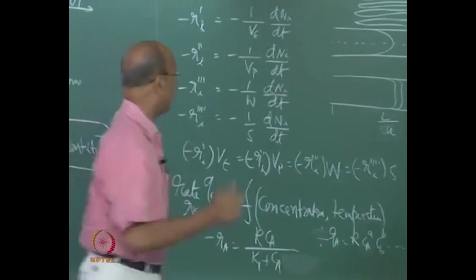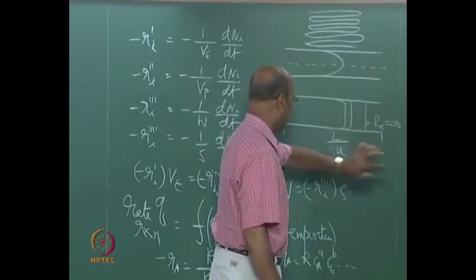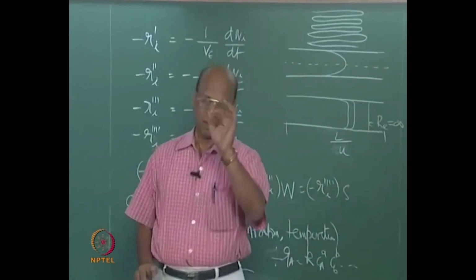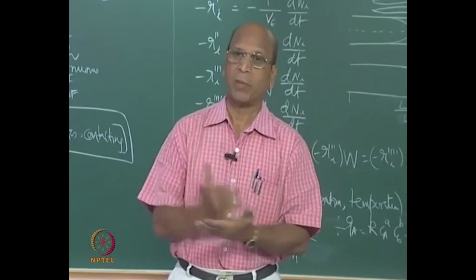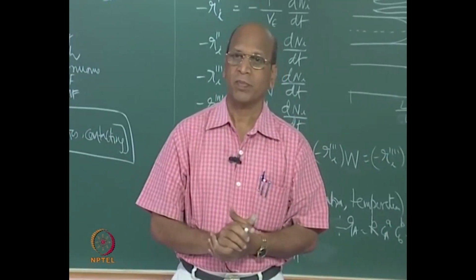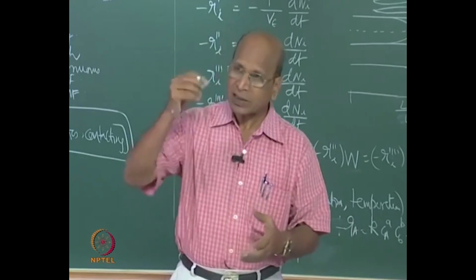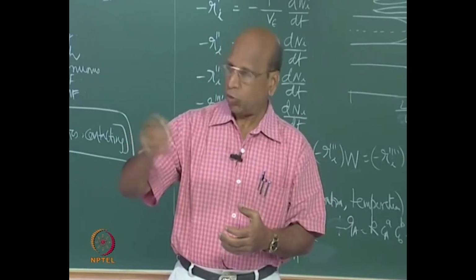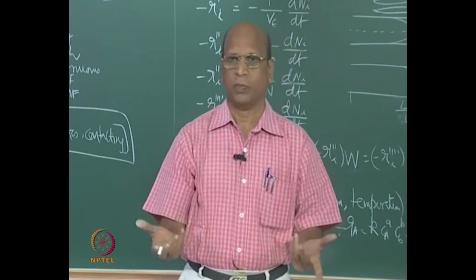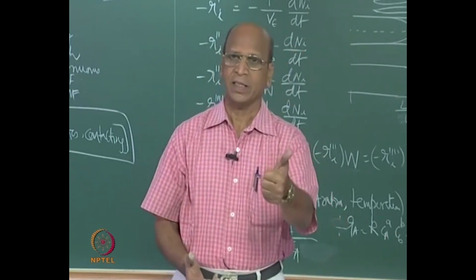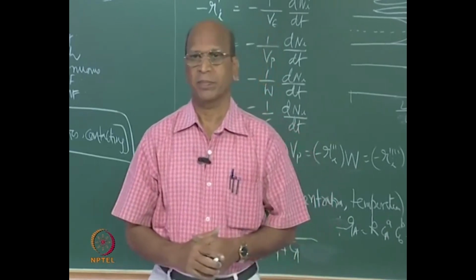So, that is why you have to choose the plug flow reactor for residence times which are very small, and most of the time that happens only for gas phase reactions. And if there are some liquid phase reactions whose reaction times are very small, there also you can go, but criteria is time. That is one thing.